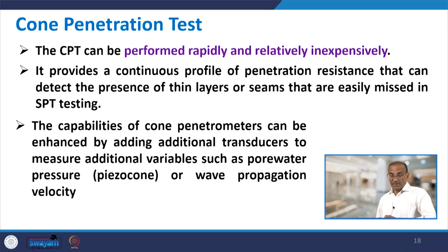The CPT can be performed rapidly and relatively inexpensively, because in CPT you are just continuously pushing inside. You are not taking it out, because no sample is collected in this case. You are just pushing your penetrometer at a certain rate into the ground.